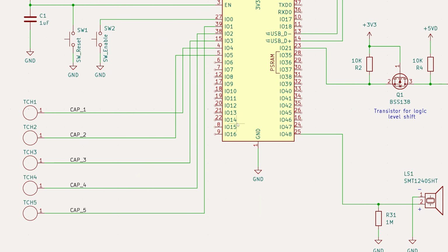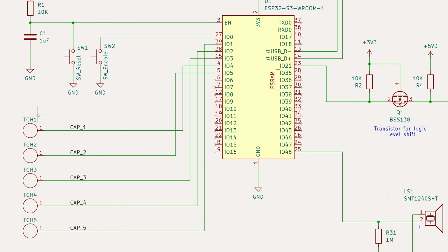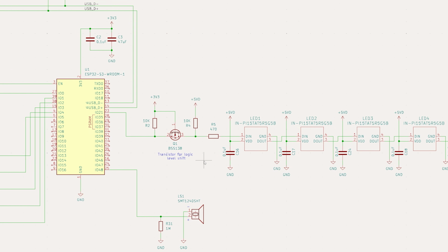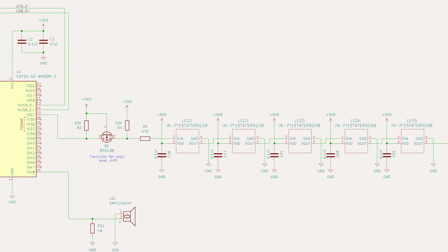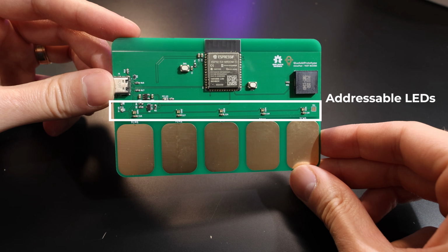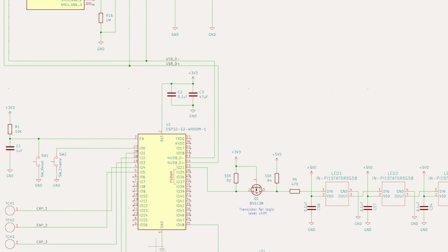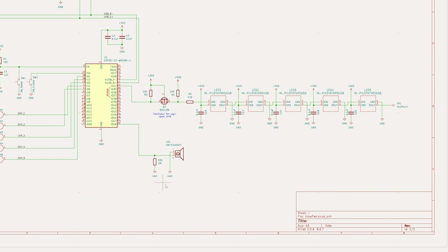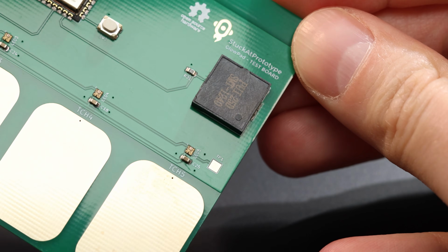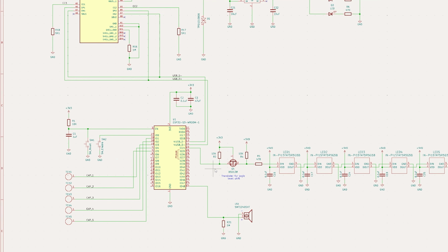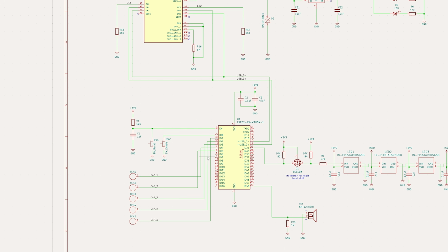We've got an ESP32. We've got capacitive sense buttons that are attached. We've got a chain of addressable RGB LEDs. We're talking to the device via just a USB here, so we're talking native USB on board. And we've got a piezo attached to one of the pins here. The goal is to simply bring up this board, meaning get the LEDs working, get the piezo working, get the capacitive touch working, right? And then see if we can actually go any further from that.